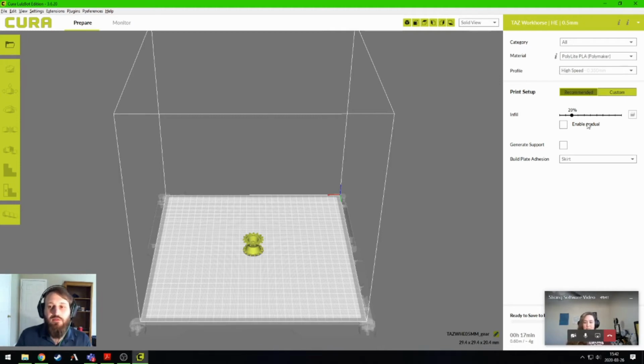With infill, this is your infill density. So how much material is being used between each wall that's generated. This is usually done in some sort of cross pattern or honeycomb pattern or something like that. But it's going to be material that provides structural support. And it's almost like, I'm trying to think of another real world example, a honeycomb structure within bumpers and stuff like that. So it's that crush support, if it falls or something.